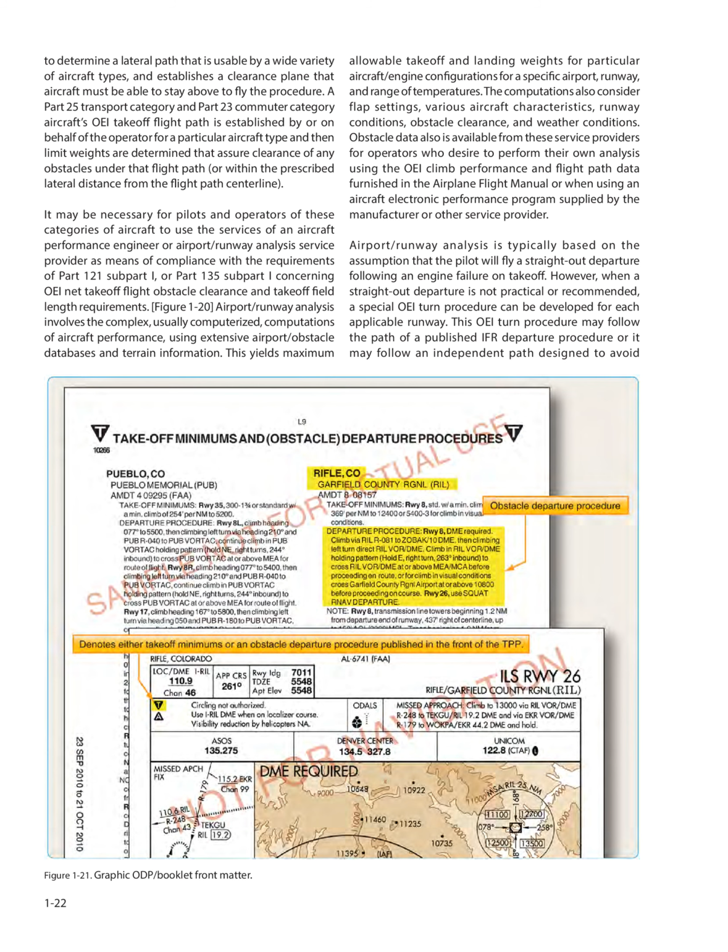Obstacle data also is available from these service providers for operators who desire to perform their own analysis using the OEI climb performance and flight path data furnished in the airplane flight manual, or when using an aircraft electronic performance program supplied by the manufacturer or other service provider.